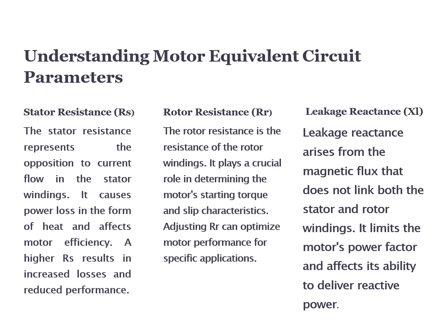Next we have rotor resistance. It is denoted by R subscript r. This parameter plays a significant role in determining the motor's starting torque and slip characteristics. By adjusting this resistance, we can optimize the motor for specific applications such as high torque starts or smooth operation under load. Finally, leakage reactance, that is XL.